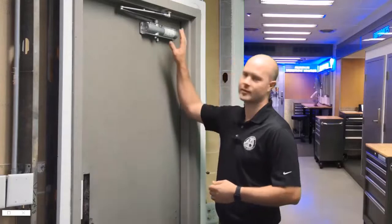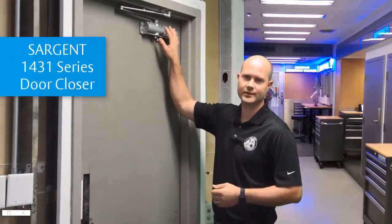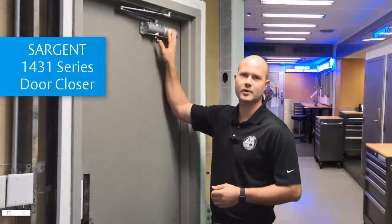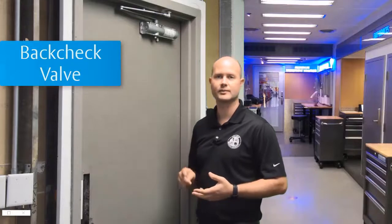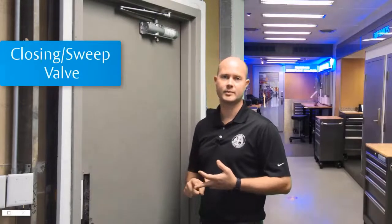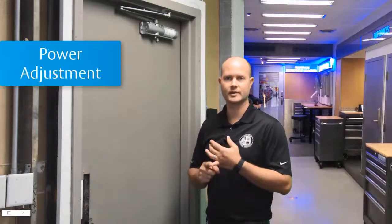The door closer that I'm going to show you how to adjust today is the Sargent 1431, but this would work the same way with any of our models with ASSA ABLOY, Norton, Sargent, Corbin Russwin, Yale. Any of those would adjust very similarly to this, as long as we have a back check valve, a closing or sweep speed valve, and a latching valve, and a power adjustment.